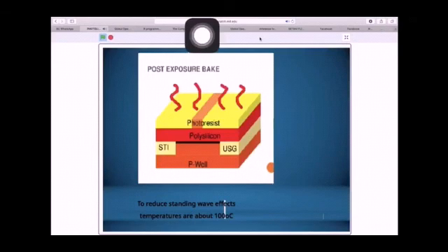Post-exposure bake, or PEB, is the process to smooth rough feature sidewalls caused by the standing wave characteristic of thin film interference in a monochromatic exposure process. This process is so important that skipping PEB will result in no pattern or a very faint pattern after develop. In both types of photoresist, PEB improves adhesion and dry etch resistance since more solvent is removed from the bulk film.